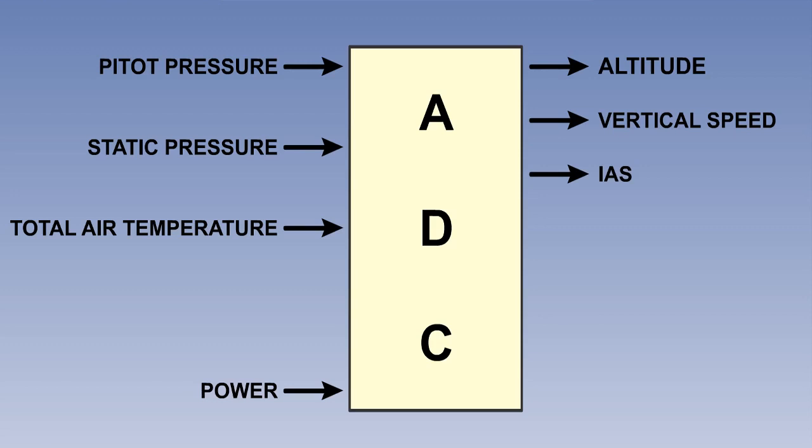However, because this newer technology is manufactured to higher tolerances than previous direct reading instruments, instrument error is very small, and what there is can be accurately measured and corrected. Position error can also be incorporated into the computation process, and therefore the output is presented as calibrated airspeed in many systems. The total air temperature can be shown. But again, with a computer, this can be converted to static air temperature without the need for calculation by the aircrew. The computer now has all the information it needs to calculate true airspeed and Mach number.